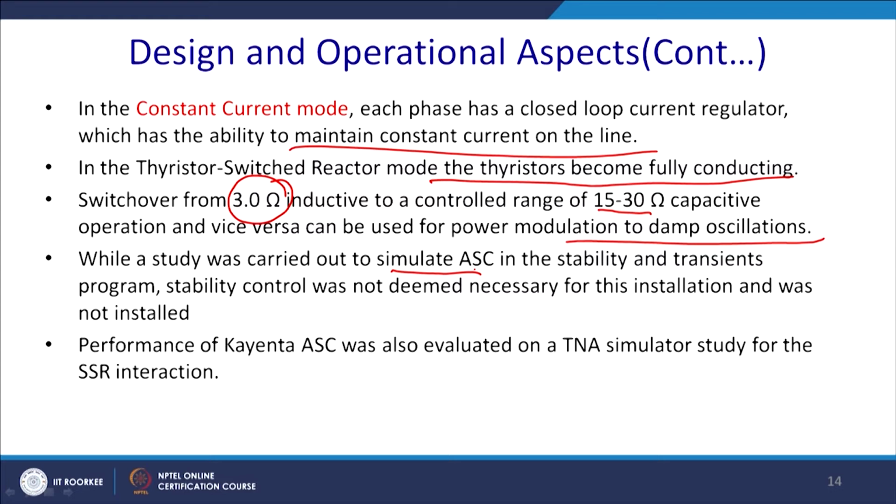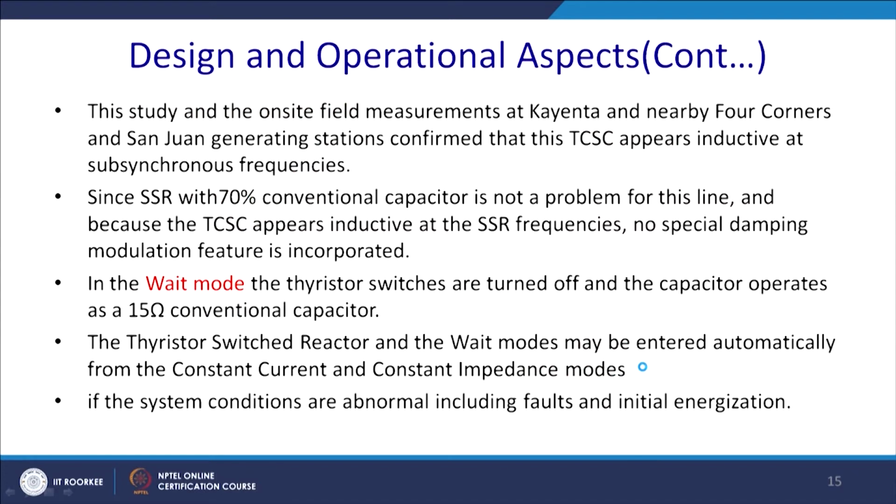The performance of Kayenta TCSC was evaluated with another software, the TNA simulator, with the SSR insertion. It was found from the study and the on-site field measurement at Kayenta and the nearby Four Corners generating station that this TCSC appears inductive at the subsynchronous frequencies.